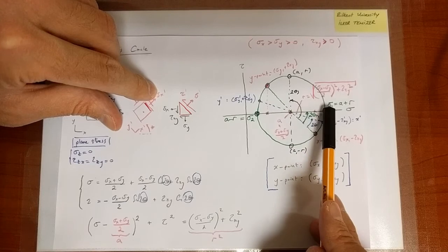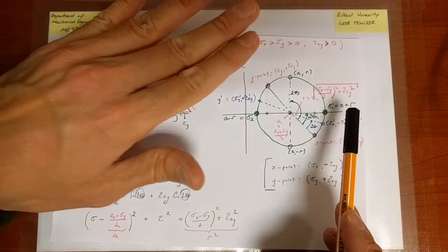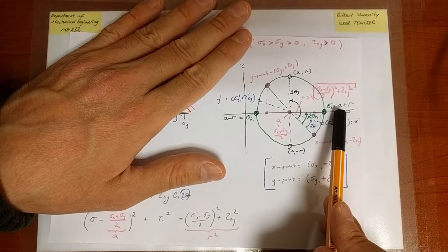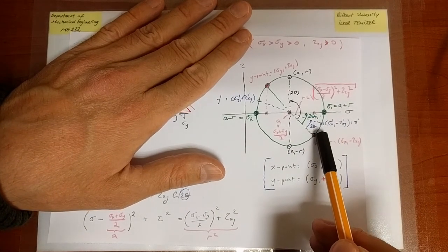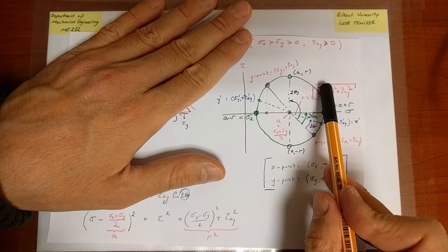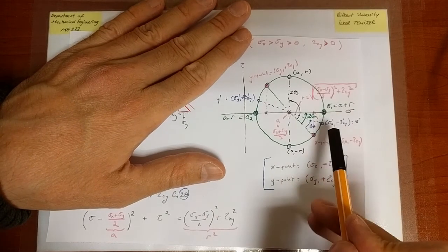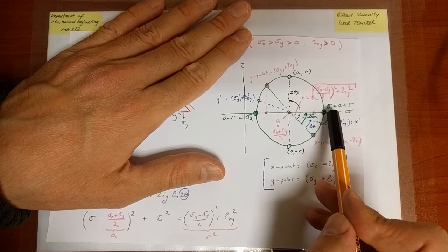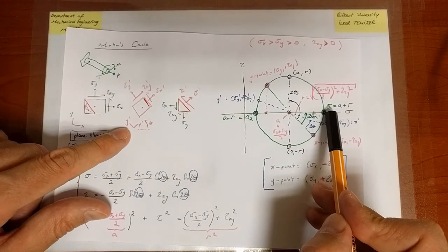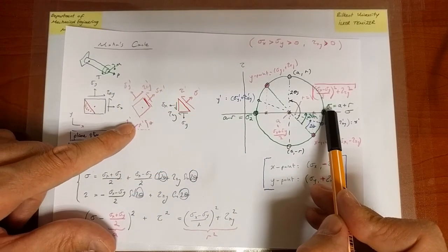So in other words, if I look at the Mohr circle, if I plot everything like this, I'm predicting that if I rotate in the counterclockwise direction, the sigma x value is going to increase towards the principal direction. If I want to predict that correctly, that's what turns out to be from the mathematics, right?